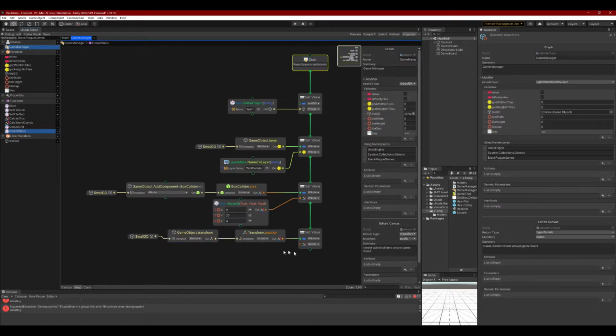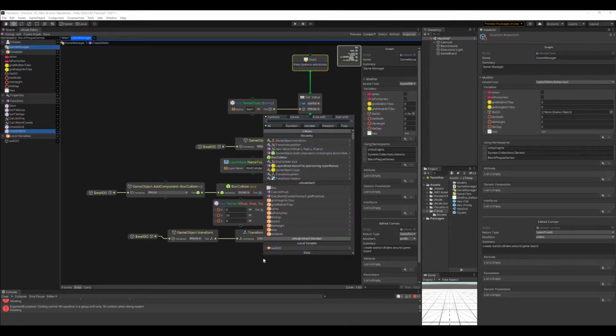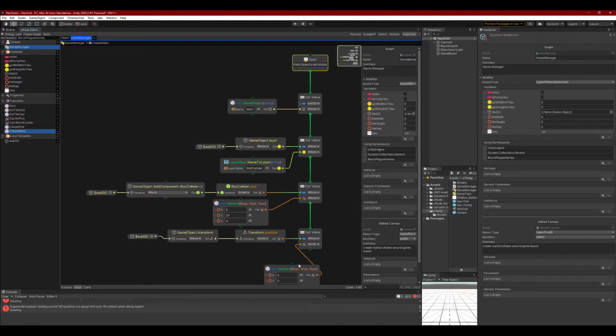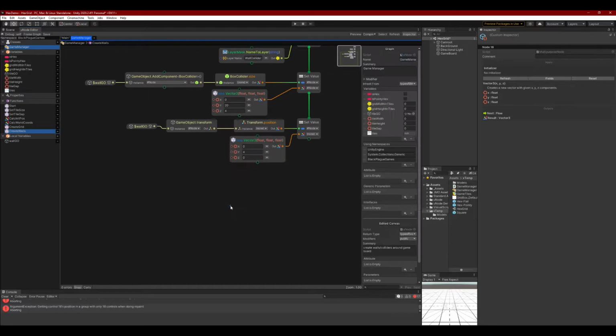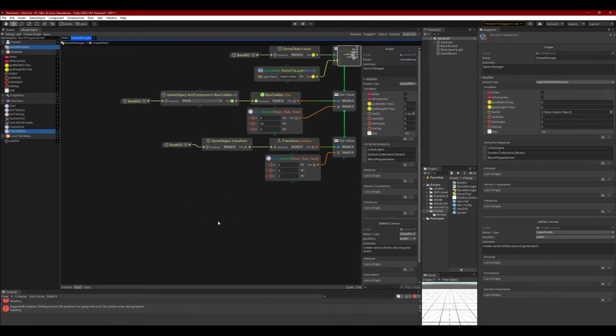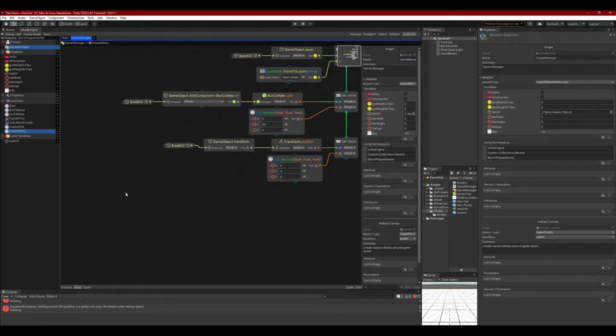Now we will define a new vector3 on where we want that located, and that will be based off of the grid width and tiles as well. So go ahead and you can drag from the set pin value, select a new vector3 with the 3 float options.